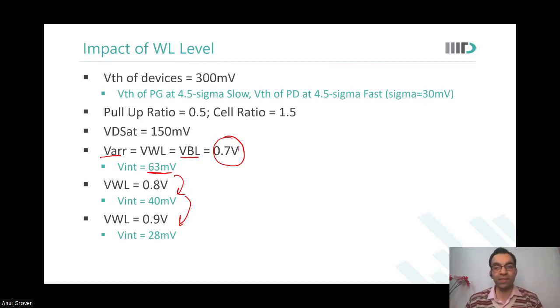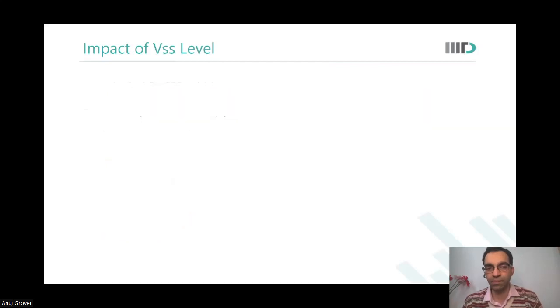You can use it in mux 1 though. So the paper that I was mentioning to you about, where we use multiple read and write assist schemes in parallel to go to very low voltages, in that paper you will see that we are doing something of this sort. We are using word line boost. We have a physical mux 4, but we have an electrical mux 1. So just go and check out that paper. It's a very interesting paper.